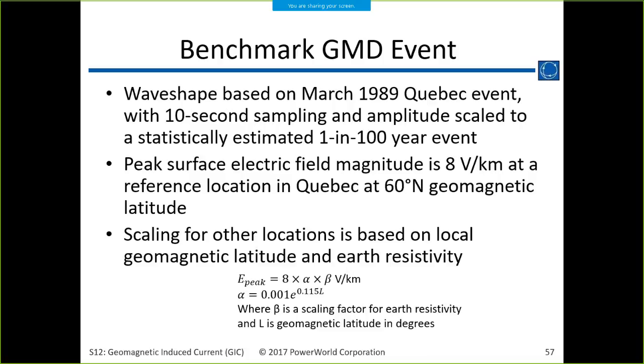So if you wanted to recreate the event with tripping, you would probably have to enter those events, maybe in the transient stability tool or something like that. It's not going to automatically come up with that. Certainly not in the power flow side. Well, but it would see the same things that they saw as far as whatever they had measured. That was part of the problem. They didn't really have a lot of measurement.